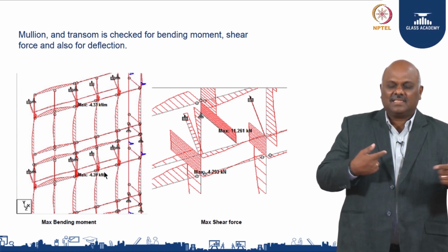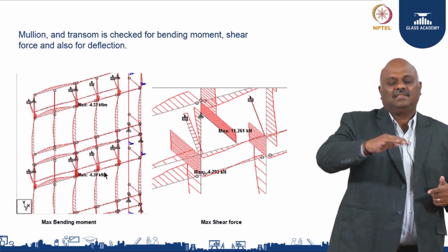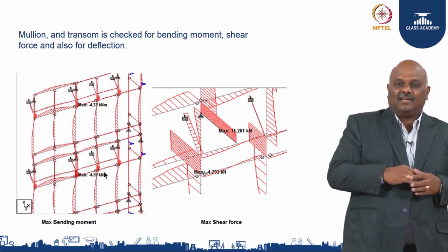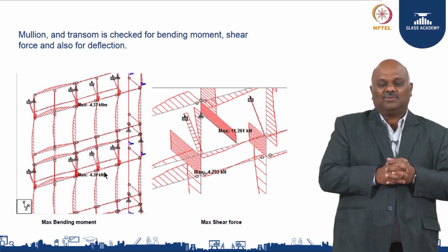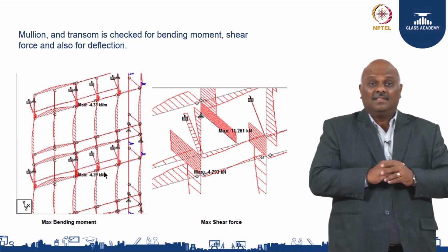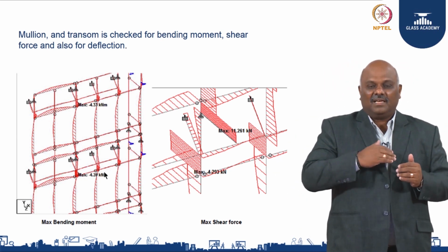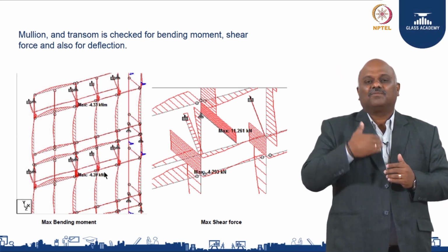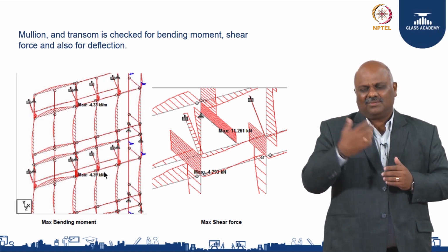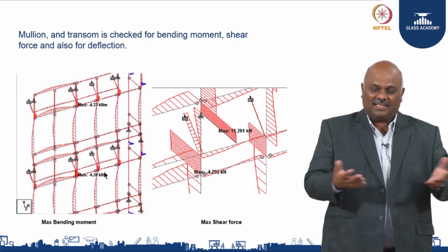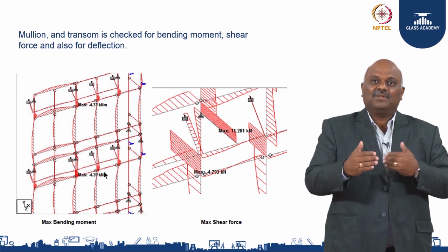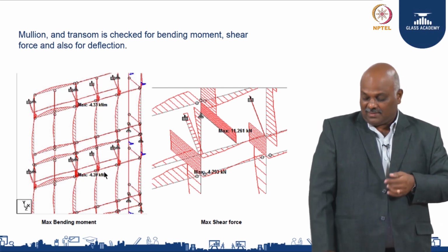So, understanding the depth against the wind and dead load: dead load is very minimal, we do not have to take that into consideration, but your main criteria will be against the wind. What is the load? Because that factor will be more. Sometimes the dead load can be heavier if you put heavy stones or anything, but most of the time when you design it is against the wind.